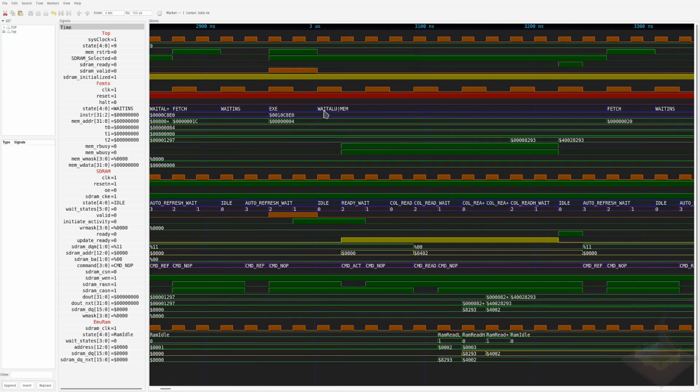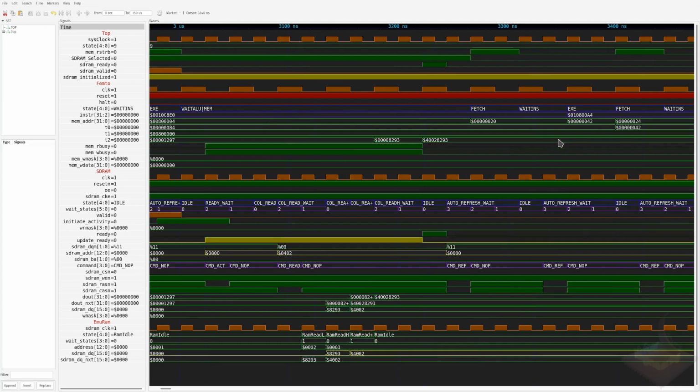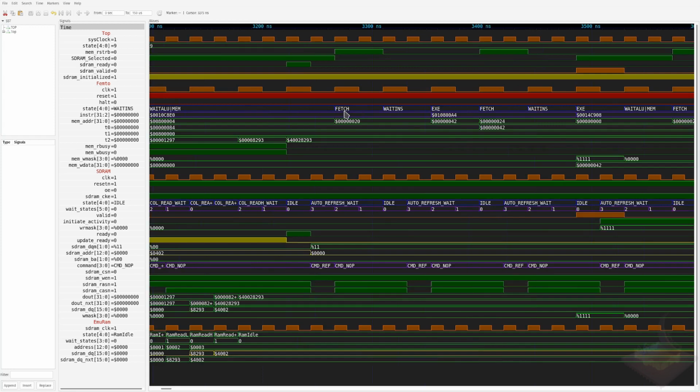You'll also notice up here that because the signal went high, the Femto now goes ahead and sits and waits. It's not actually doing anything but waiting, and it won't fetch and execute the instruction. In this case I'm not actually loading an instruction, I'm loading the T2 register with data, just to show that we can load memory using the sequence. You can see it's waiting as it reads the low half word, then the high half word into it. When it all has it, it drops its flag, and the Femto recognizes that and moves right along.